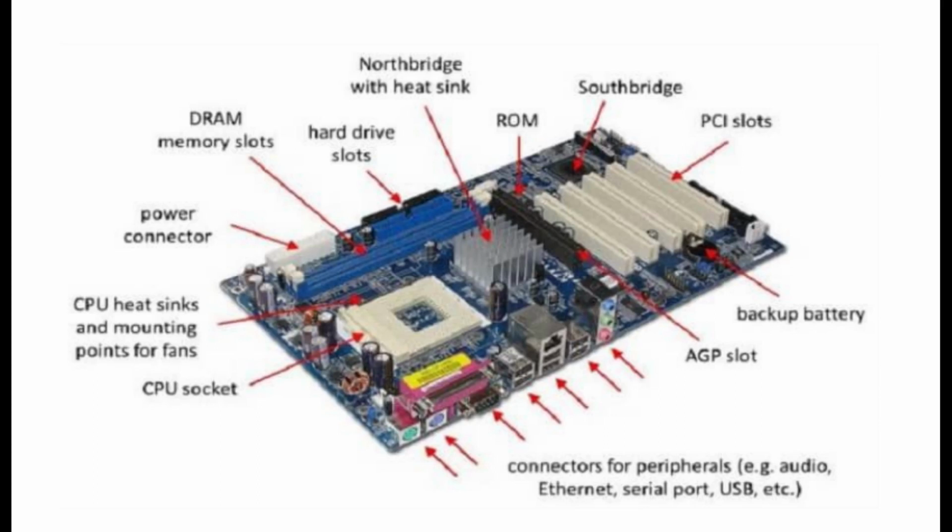12. Power connector. The power connector provides an electric supply to the computer to function as intended. The power supply connector has 20 pins and converts 110V AC power into +/-12 volt, +/-5 volt, and 3.3 volt direct current, DC, power. Functions of a motherboard.